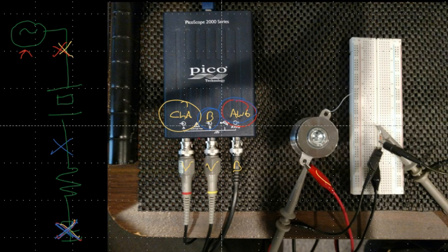As you can see here, I outlined this in the schematic. We have the red part, which is the arbitrary wave generator. We also have channel A, or channel 1, being measured. Then we have a wire which is going to a resistor. This resistor is 325 ohms. We have channel 2 measuring the voltage over that resistor, and right there is the ground plug, or the ground clip, of the arbitrary wave generator.